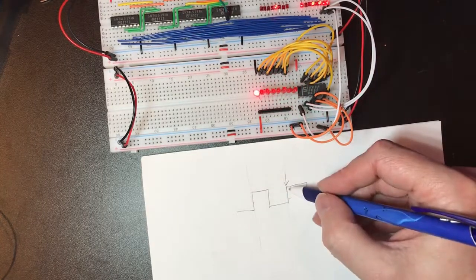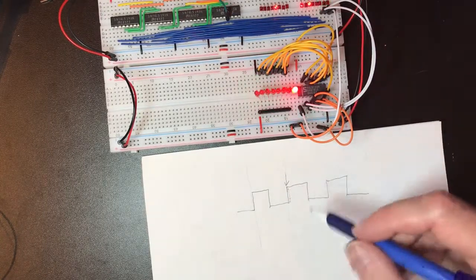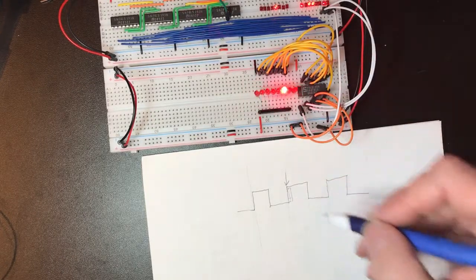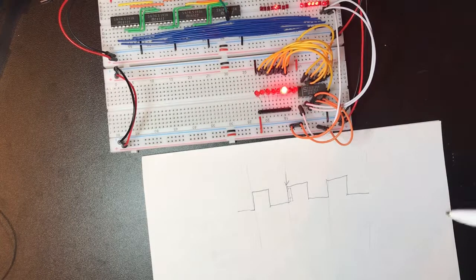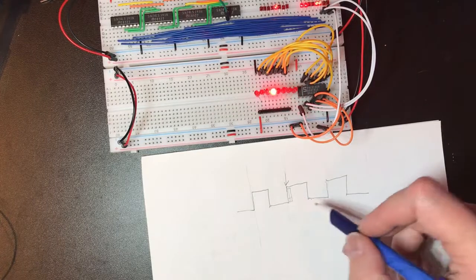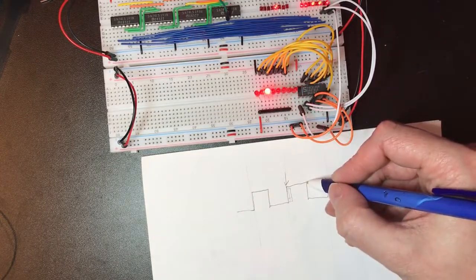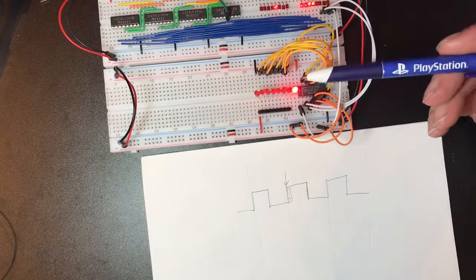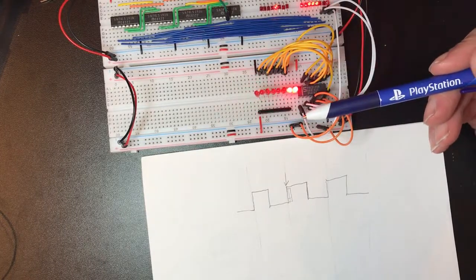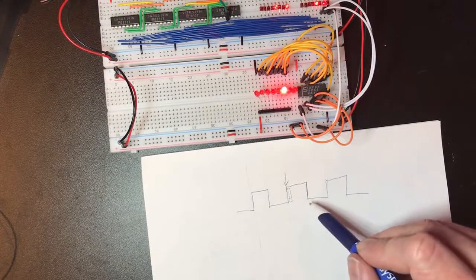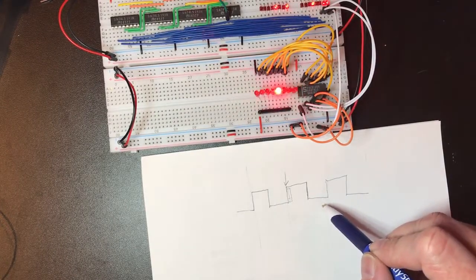So there's going to be a little chunk of time where the register is resolving its output. But to be honest, that can happen over this entire space if it needs to, because here on the falling edge of the clock is where we would like to tell a register to load. So we've got this time for the value to be asserted to the bus, and then this period of time for it to get pulled back in.